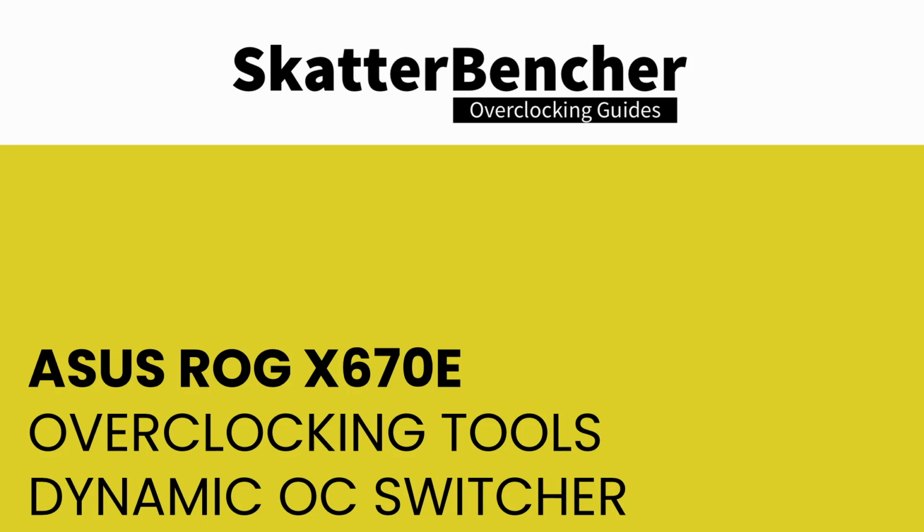Dynamic OC Switcher, or DOS for short, is ASUS's very clever way to work around the most fundamental problem with AMD Ryzen CPU overclocking. It was first introduced on the Crosshair 8 Dark Hero motherboard and has since been introduced on several other ASUS ROG AMD motherboards.